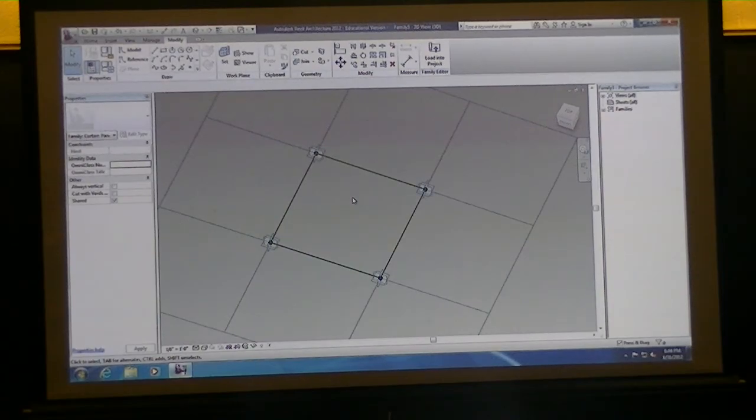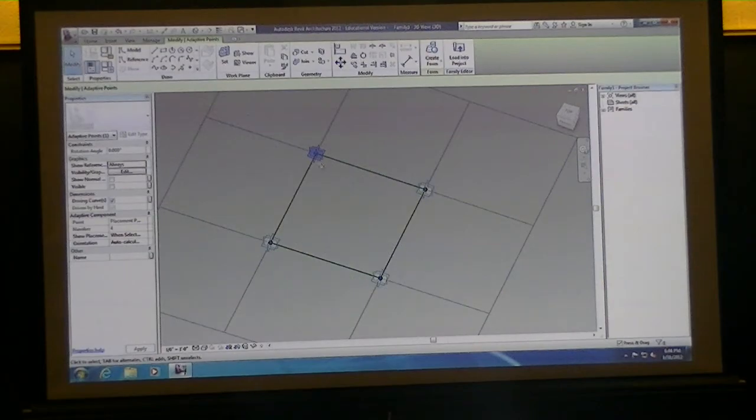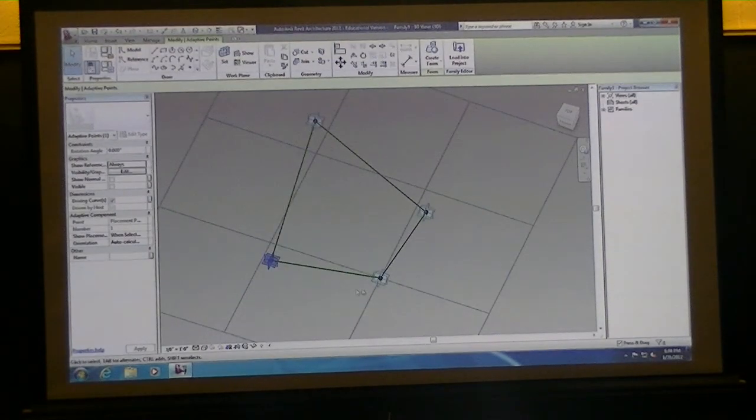As soon as you start to try to bend this over a complex surface, and you start doing offsets and all these other ideas to make a pattern in here, it might fail unless you take each one of these points. I'm just going to take one of these and let's drag it up, drag another one down, and basically make it so that nothing is parallel to the work plane.